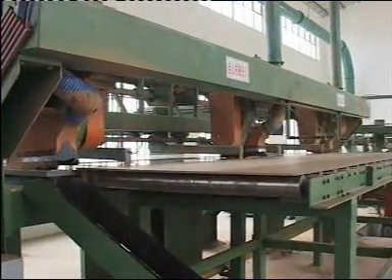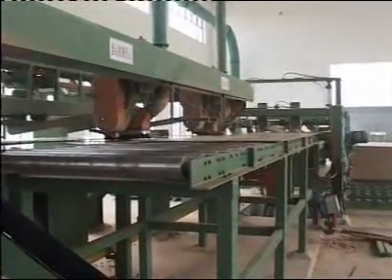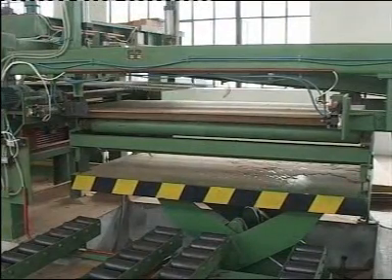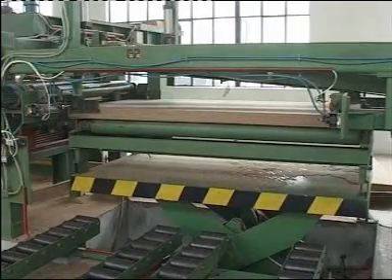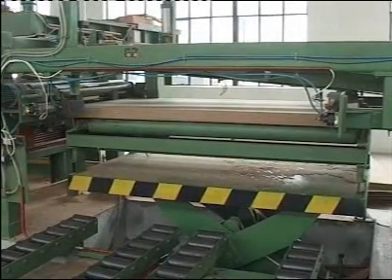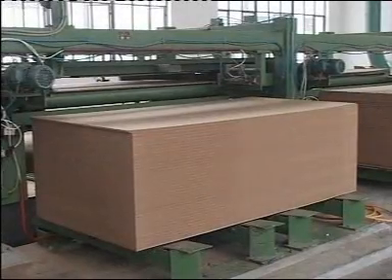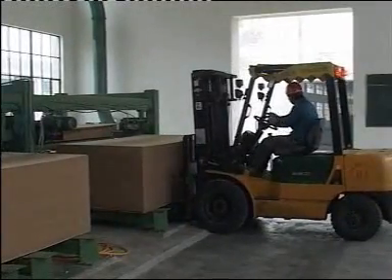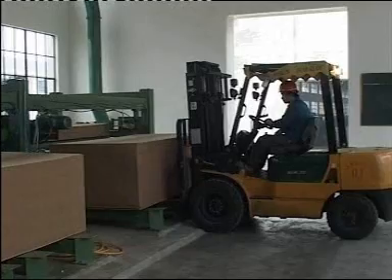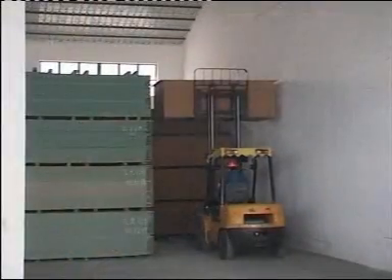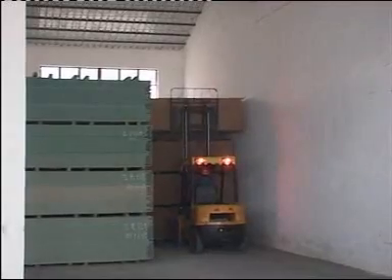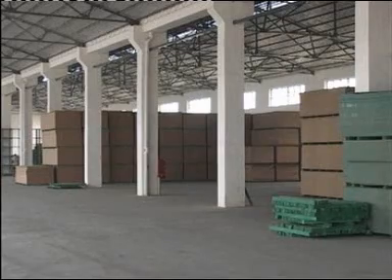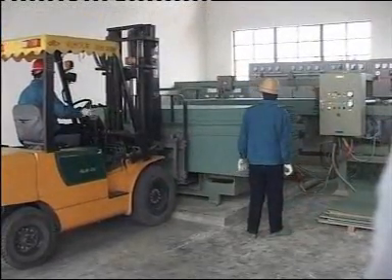The cut-to-size boards are then transferred to centering device and hydraulic lifting platform via the outfeed roller conveyor. When stack reach to preset height, hydraulic lifting platform will automatically discharge the boards to fork roller table and then transported to semi-final product warehouse. Board will be stored for a period of time to uniform board moisture before sanding.